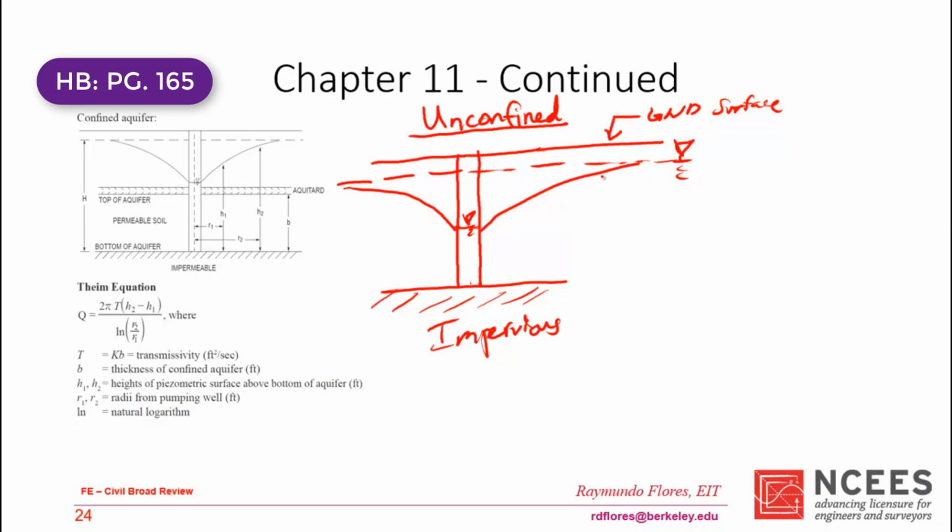So it might start off here, where the curve is this way and this way, but as it progresses, it's gonna keep going up. So maybe you might have this one, and then this one, and I'll erase these, but you start off that way. And so this is just a representation for where the water is typically in the pipe, just at any given moment. But the idea here is that because it's unconfined, we would expect that the water flow is all throughout the length of the pipe. And so this represents the water flow.